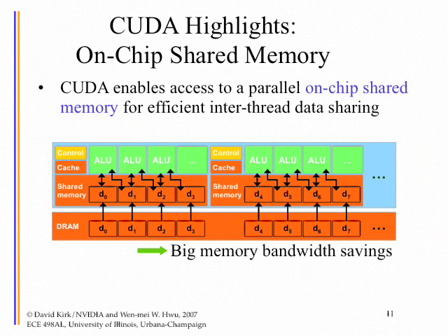The bandwidth out of the DRAM is actually pins. We're talking about GPU pins, and those pins are expensive. A typical high-end chip that goes out today has about 86.4 gigabytes per second, and the next generation will be right around 100 gigabytes per second between the GPU and the DRAM.